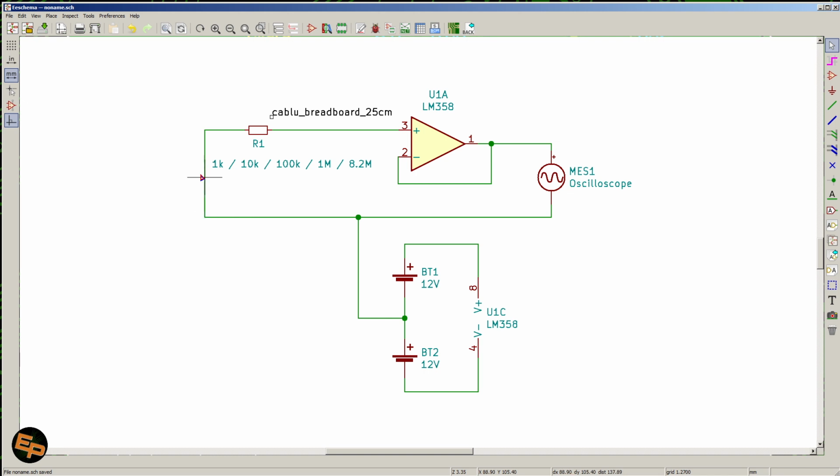You know, if we have a DC voltage on the input, like we will have in a near future video, when I'll show you how I've built a device that sadly must have a high impedance on the input, then we can use an RC low pass filter on the output and basically try to mitigate this problem, because my signal is just a DC voltage in my case.